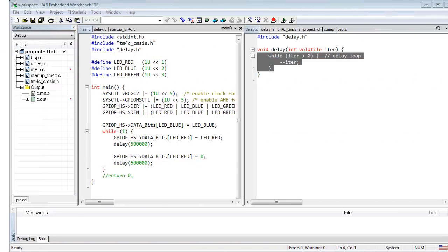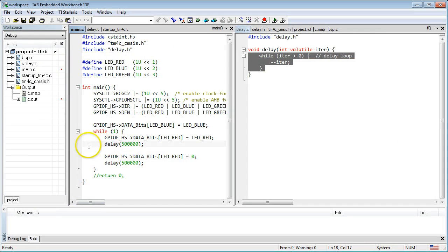With all this new information, you are almost ready to get back to the code and use the SysTick interrupt instead of the brain-dead polling. But before you set up the interrupt, let's modify the polling code so that you have only one delay in the loop. This one delay would then directly correspond to the interval between the SysTick interrupts. So the body of the loop, except the delay obviously, would be the exact code for the interrupt handler.